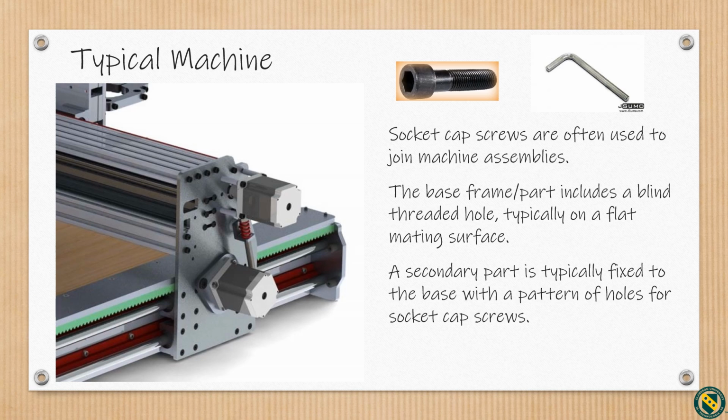We can see how use of non-permanent joinery allows for ease of assembly and disassembly, possibly replacement, maintenance, repair, or just adjustment. Note that socket head cap screws are commonly used in assemblies such as this that don't provide sufficient clearance for a conventional wrench or socket.